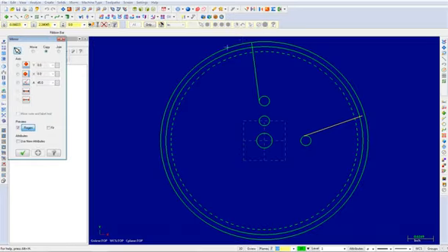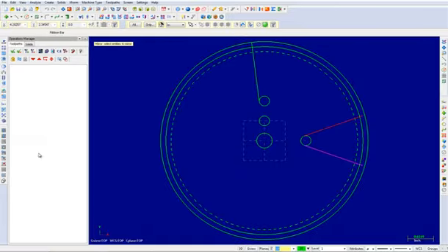The Mirror dialog box will appear. In the Mirror dialog box, ensure that copy is enabled and pick the option to mirror about the X-axis. Once complete, pick the Apply button to select the next line to mirror. Select the following line.